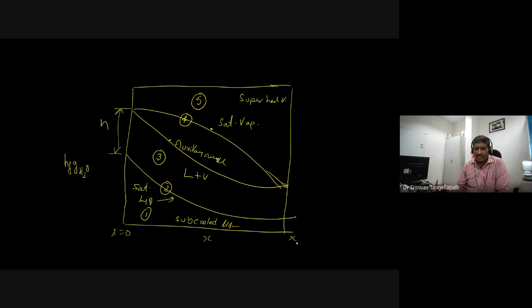And if x is equal to 1, that is completely ammonia. This shows the latent heat, that is HFG of NH3, ammonia. So between the latent heat of water and the latent heat of ammonia, based on the concentration changing from 0 to 1, the latent heat of this mixture will change. According to the change in the mixture, the gap is also varying here.